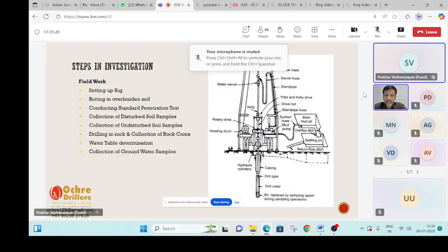So we surveyed the locations of the piles. After surveying and taking the new layout, we selected some piles that could be used, discarded some piles, and added some piles. For the changed column layout, we had to do this kind of adjustment.